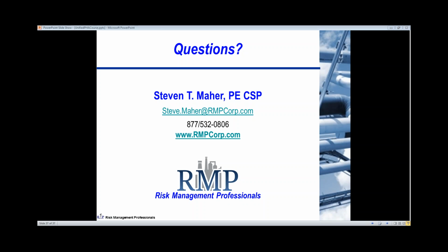However, how that's evolved is it's more common right now to infuse the LOPA right into the HAZOP study. For example, as you're looking at one specific scenario, and the team's warmed up, they understand the process, they've thought through the process dynamics, and then to go through and use that understanding and clear definition of safeguards as IPLs and clear definition of consequences as ultimate consequences. If you're careful with structuring the HAZOP, which you should be anyhow, segueing that or transitioning that to LOPA is very straightforward.